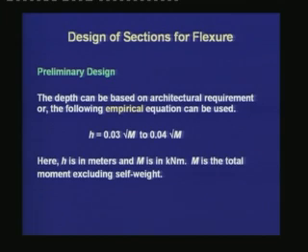The selection of the depth of a beam usually is governed by the architectural requirement, depending on the headroom clearance that is required. But if the architectural requirement is not given, then we may start with a preliminary estimate of the depth of the beam based on the empirical equations. Now we need to check this again in our final design, whether the depth is adequate or not.